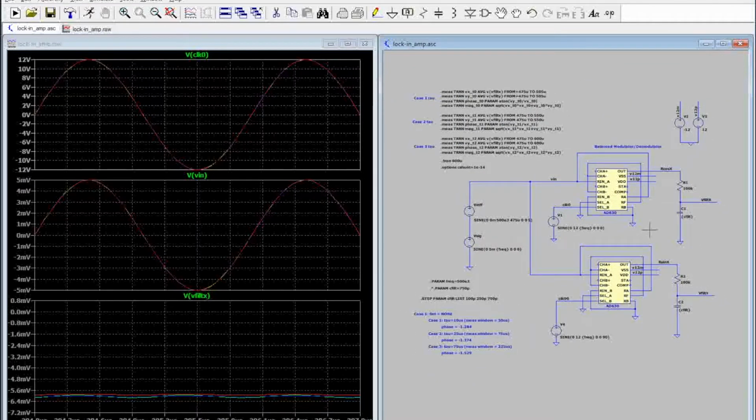So next, I'm going to put in an interfering signal at a frequency which is quite far away from the reference, from the signal of interest. So what will happen is that the phase will be chopped up by this clock, which is at the signal frequency, and the effect of this out of band noise will hopefully not interfere too much, because the amount of energy contained in the in band of the signal is going to be fairly small, and the phase variations will be random around the point where you want to actually do the measurement. So let's look at that case next.